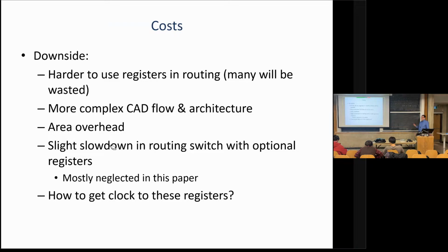So that just says it's challenging, even for the CAD engineers. And that does make it usable, because he would have actually liked to pipeline so deeply that he exceeded the logic block register count, but the CAD flow couldn't support that in a very optimized way. Anyway, that might be getting too far ahead. But anytime you add something new, like a routing switch, there's going to be some cost. So there's going to be some slowdown.